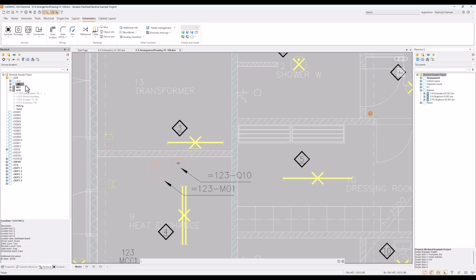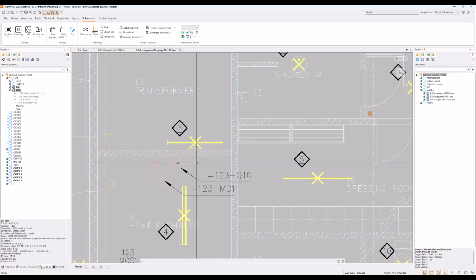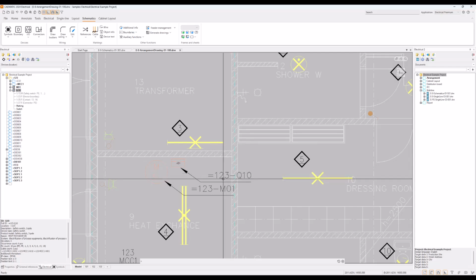And then regarding this location, you can find a motor and a safety switch. So they are not part of this distribution board, rather they are their own devices. And again, make sure you understand the full ID. You cannot have any other full IDs. I can have in this same drawing 1 through 4 Q10, and that will be its own device. But if I add 1 through 3 Q10, it will be another occurrence in the same drawing. But no more devices will be in the database.